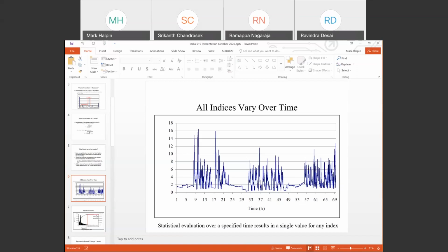So if you think about this type of variation, certainly at some points in the measurement interval, the y-axis numerical value, which is some kind of distortion, is at some periods well over 15. And that's probably a percentage, so let's call it well over 15%. At other times, the distortion level is down below 1%.